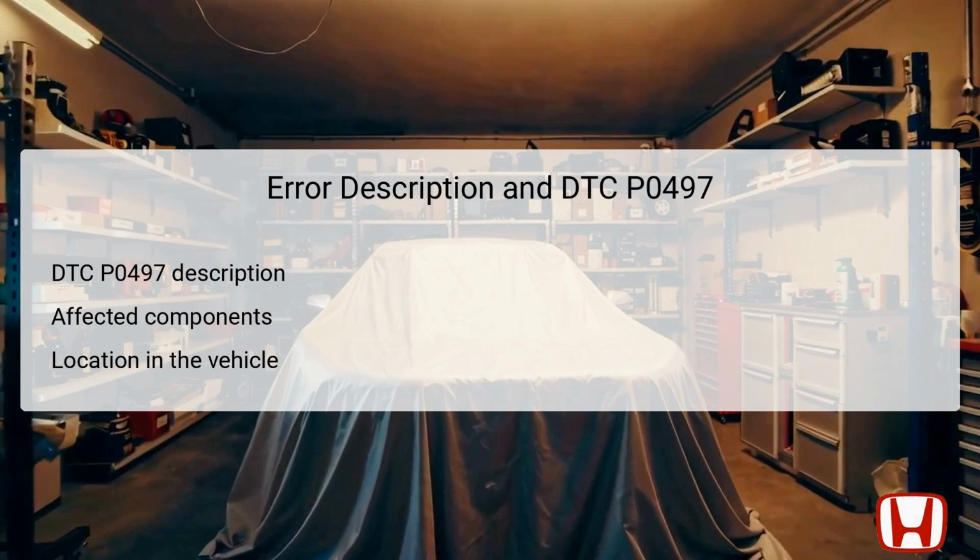The EVAP canister collects fuel vapors, the purge valve controls when these vapors are sent to the engine, and the FTP sensor monitors the pressure within the system. A thorough understanding of these components, location, and interaction will guide the troubleshooting process effectively.